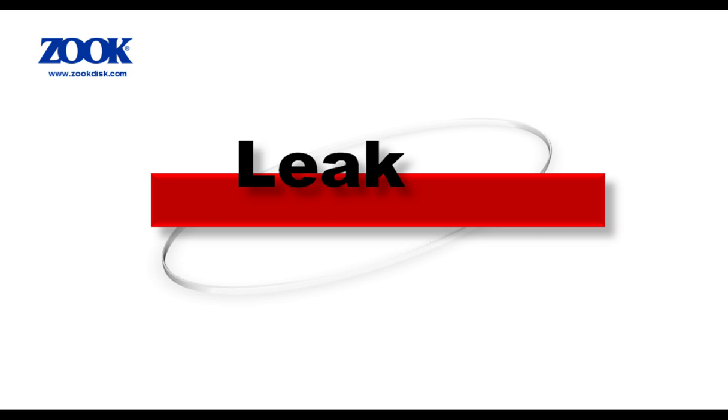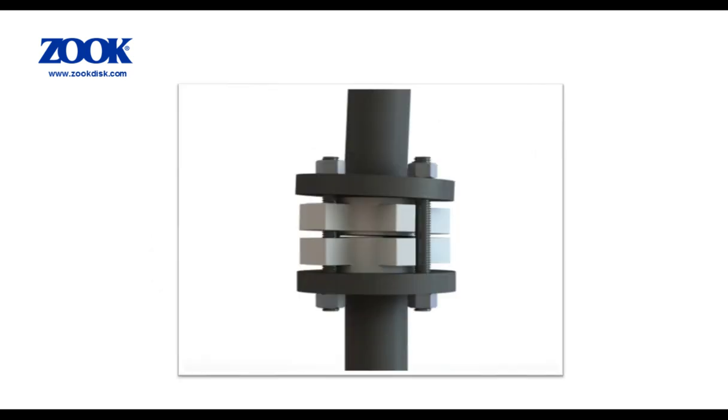It's important to realize that a rupture disc assembly is typically just a joint or a connection point in a pressurized system. All rupture disc manufacturers have recommended torque levels for their designs. Following these instructions is critical to achieve a leak-tight connection. Some disc designs are extremely torque sensitive, and incorrect torque over or under can cause disc damage or leaks. Most rupture disc assemblies utilize gaskets to seal the device into piping. Therefore, gasket style, and more importantly, gasket integrity, is a critical component in ensuring a proper seal.